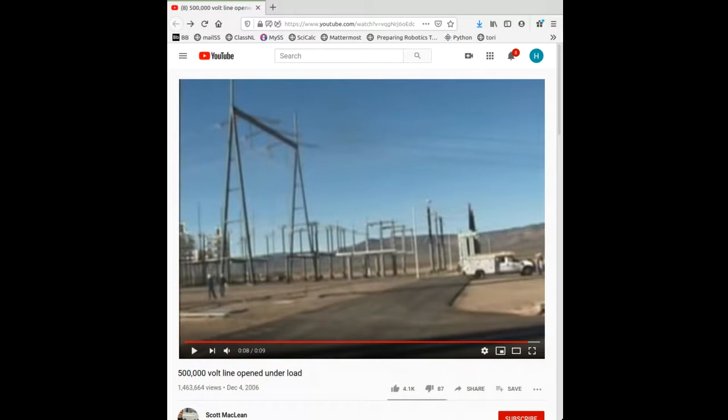You have to have circuit breakers on there to prevent too much current running through those wires. If you remember, we discussed last week when we were talking about transformers that these transmission lines are aluminum steel reinforced wires. And aluminum, if you put too much current through it, will actually catch on fire and burn.